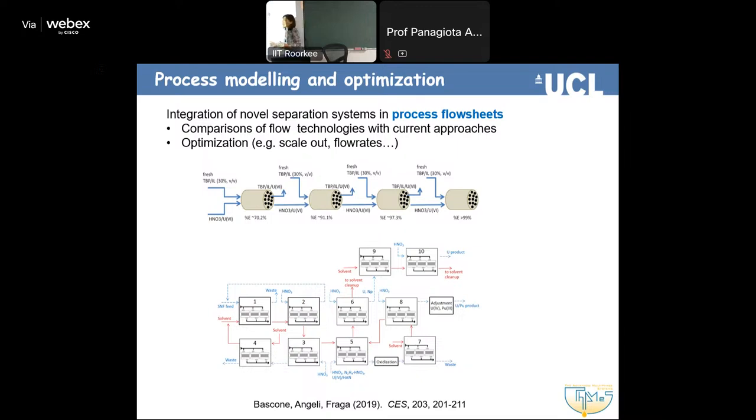And this was actually a very interesting exercise because it came back to us with some sort of findings. We did manage, for example, to reduce a lot the solvent usage here. We didn't do it with ionic liquids, we did it with conventional solvents. We managed to reduce a lot the amount of the solvent, the footprint, all the residence times were much shorter, and there were some other secondary benefits. For example, because everything was faster and the solvent was less, we were losing less solvent in the end because, you know, by reusing the solvent, you degrade it. So it's just an interesting exercise.